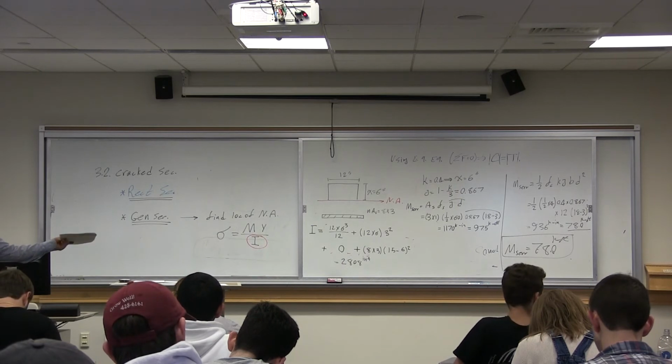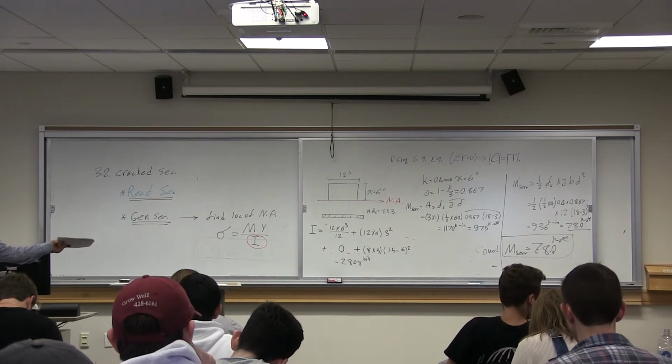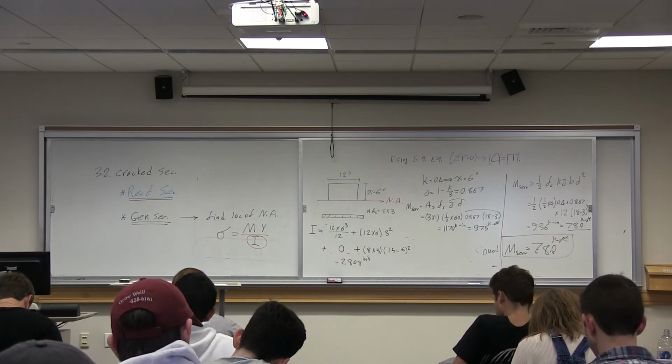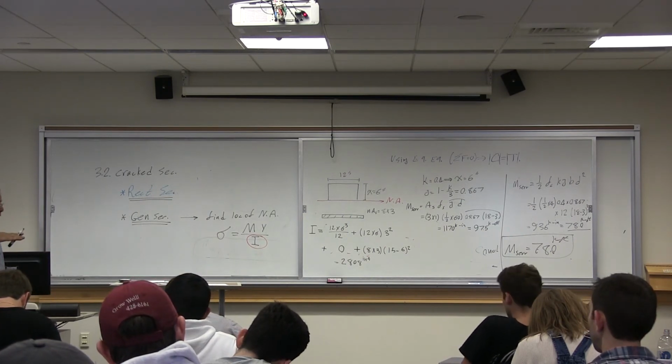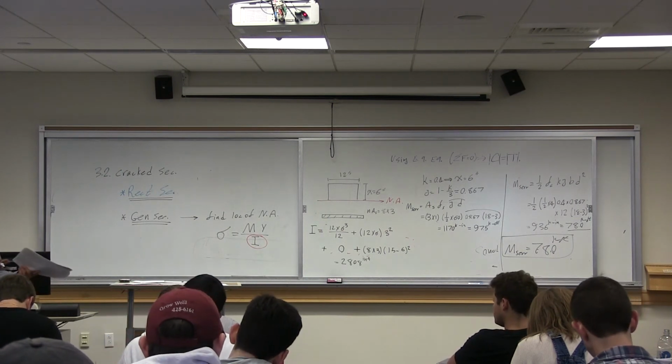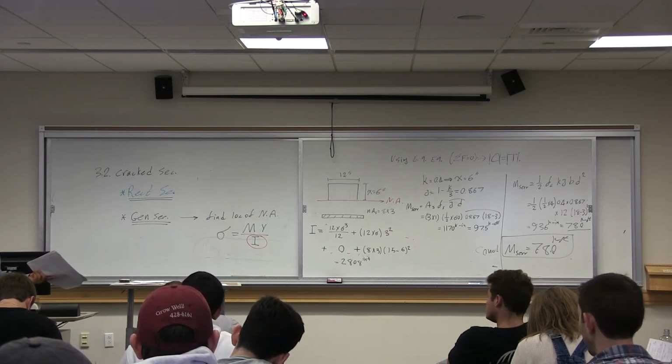So almost twice this. What does that mean? After the section is cracked, the moment of inertia drops significantly, which makes sense because there is no concrete in tension anymore.